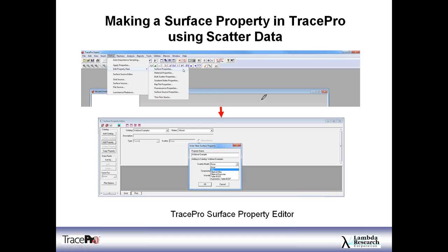In the way you make properties with TracePro, if you haven't had the chance to do it yet, you go to Define, Edit Property Data. In this case we want to do a surface property, and that brings up the surface property editor. We can pick a catalog where we want to save the material, or define a new catalog. You click Add Property, give the property a name, and then that brings up where you can define your scatter model. It's covered up here now, but you can define a temperature and a wavelength that you want to work at as well. In this case, we're going to do an ABG model.